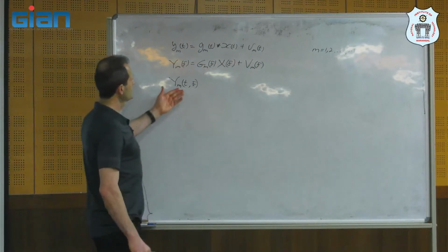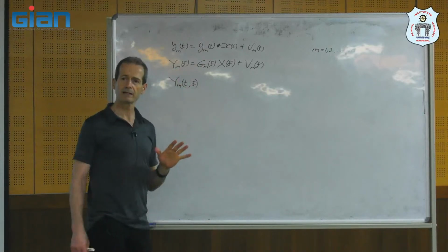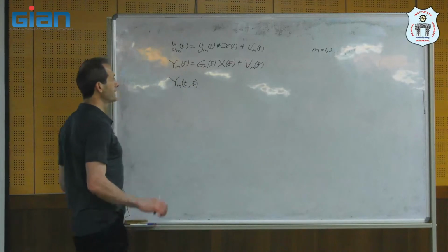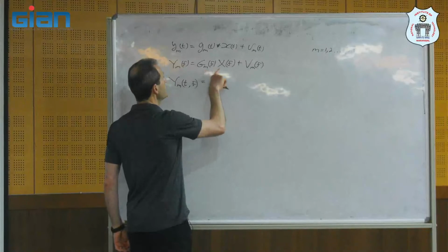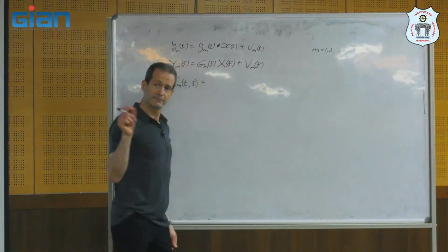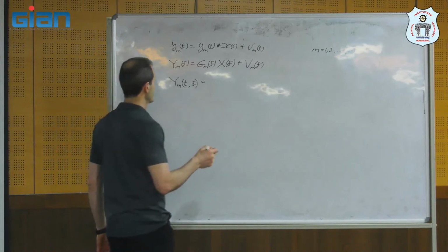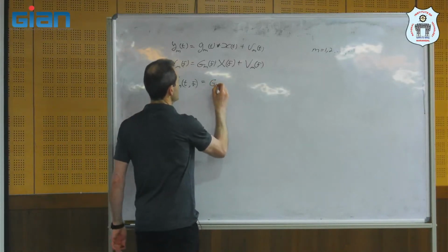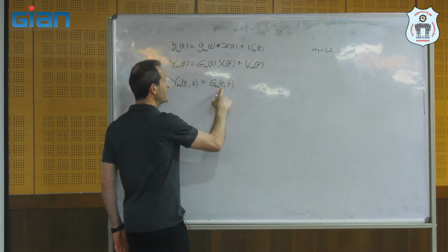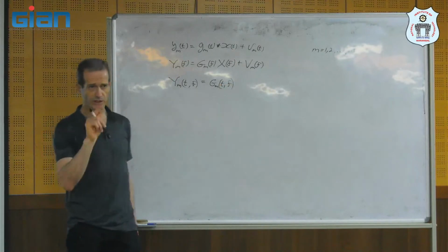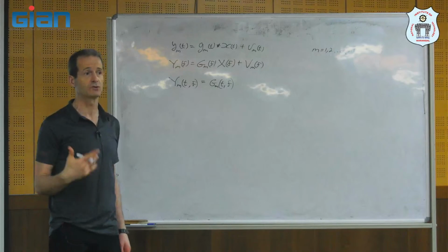And then how do we write it in the STFT domain? Sometimes people write it with a multiplication. They say, for each time-frequency bin, we multiply by a transfer function like this, G_m(t,f). The fact that we use a different transfer function for each window means that we allow the transfer function to change.